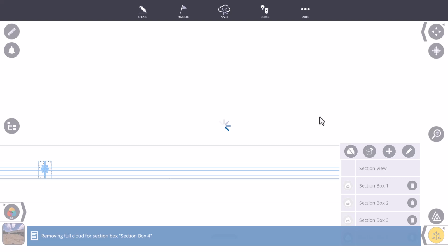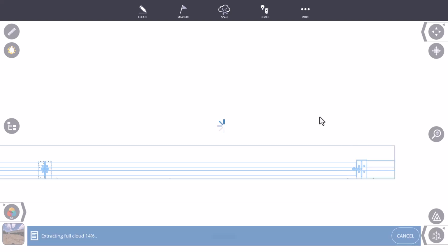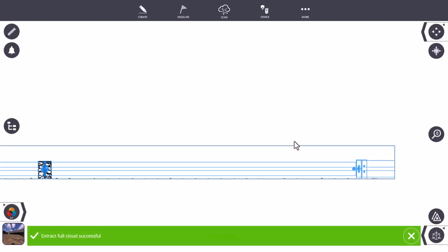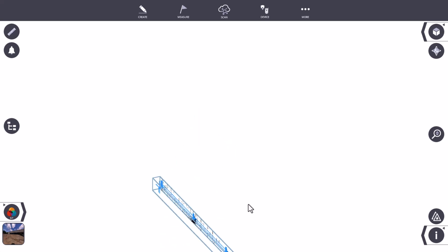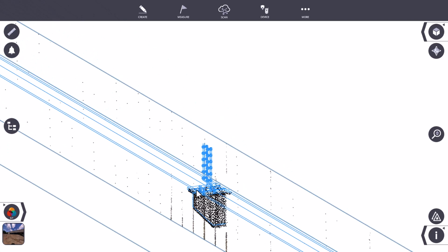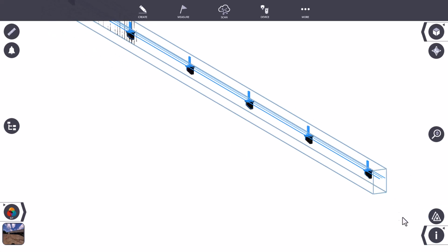this is after the fact and can still be very useful, because obviously aligning it will show me if there is an offset. If there's a large offset and I determine it's not the azimuth, then really where those were installed was not where they were designed. So you can still use it as evidence because between the scan data, it's still going to be very accurate. There we can see that looks actually very nice. All those are going in very well, and that's where the steel will go in.